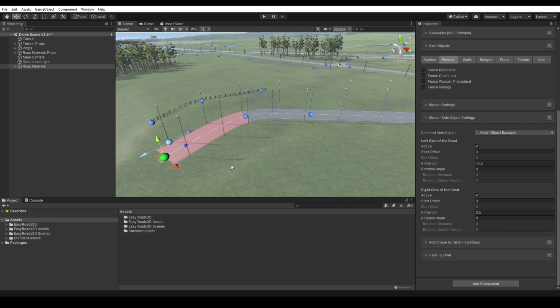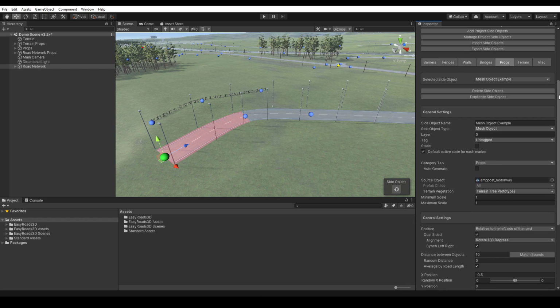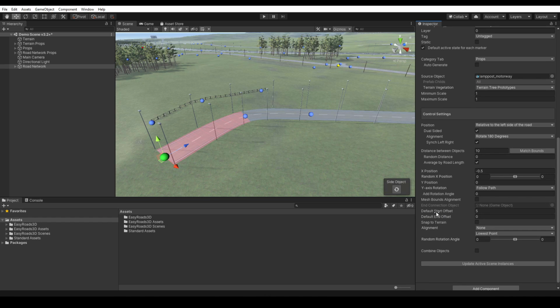Ctrl+H toggles this feature on and off. We can drag the handles to change the positioning. So this too is flexible. If offset values are always required, it is a lot more efficient to set them here as the default offset.